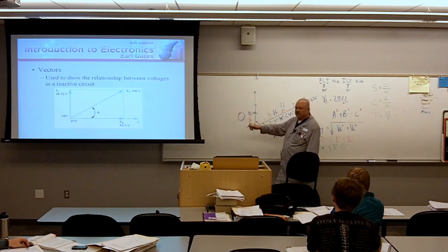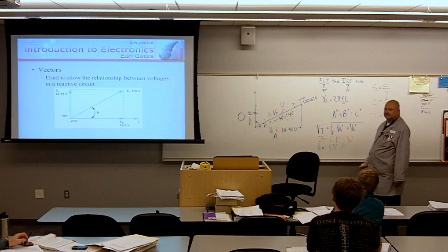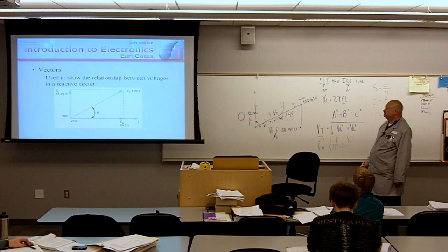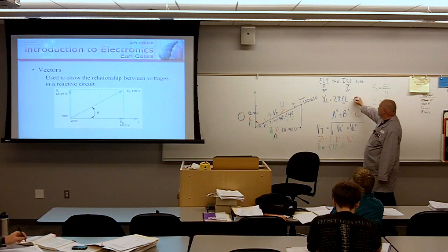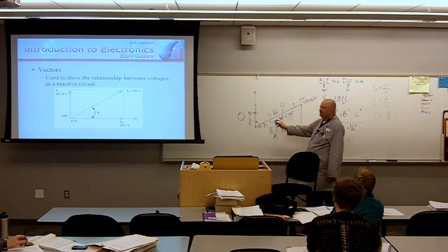If I want to make this line longer, what effect is that going to have on angle theta? It's going to increase angle theta. How can I make my opposite side longer? You want more reactance across voltage. You would bring your frequency down. If I lower my frequency, I lower my X sub L.